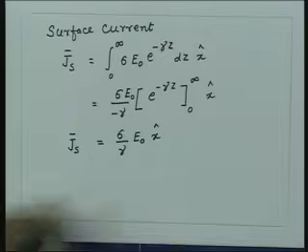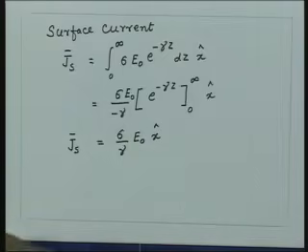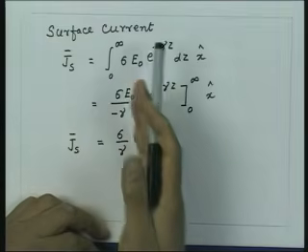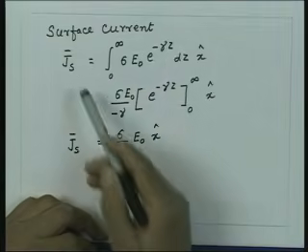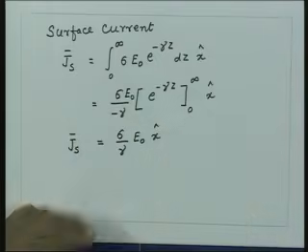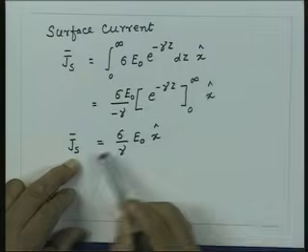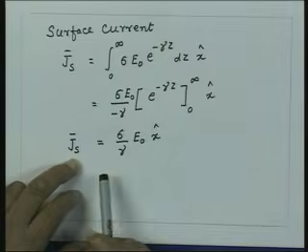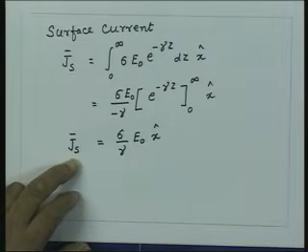Now, this quantity, as I mentioned, we are calling this surface current density. However, we have to justify completely that though this is not truly a surface phenomenon, it has all the properties which the surface current has. And one of the properties we know the surface current has is that it is related to the magnetic field, the tangential component of the magnetic field to the surface.